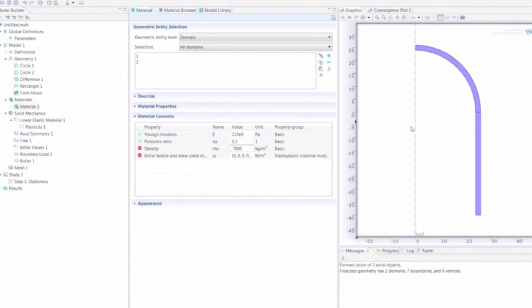I will define the first and second direction to be the same, and the third one will be the one which will be coming out of the structure. So the in-plane normal yield stress is 381 megapascal. We have two directions, 361. Then the out of the structure is slightly stronger, it's 140.